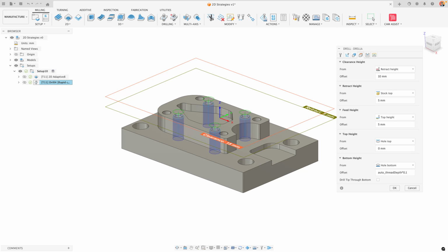Now ultimately there are so many different variables and parameters and ways that you can apply expressions and defaults within your toolpaths. It is a massive thing to go through and adjust, and typically what happens in every team is that there will be one or maybe two people who would go through and set these. But there's also a lot of teams out there where one person would set these, but then other people should really be using those same settings to develop consistency across your cuts.